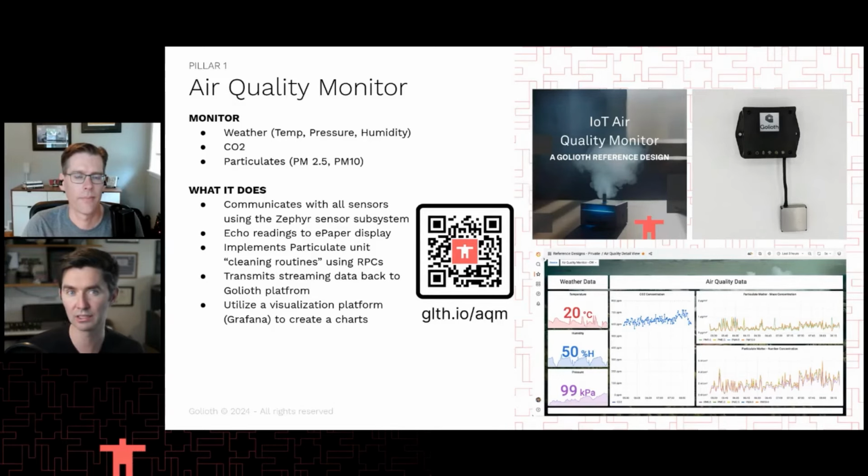It is using Zephyr's sensor subsystem, which Mike has written some great blog posts about. We use it all the time here. So, look at that as an example of how you might tie into other sensors. Say you find another sensor that's in the Zephyr tree, you could utilize it and pull a different characteristic. Like there's different characteristics in the sensor subsystem, right? Yeah, that's right. Basically you have channels, which are an abstraction layer for each type of data.